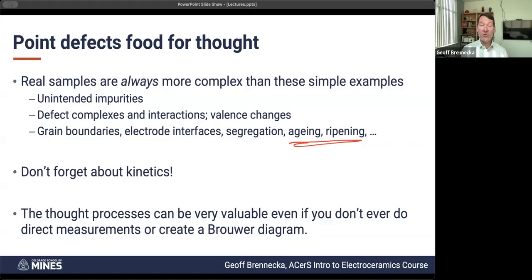But keep in mind, if you're doing these kinds of measurements, maybe your microstructure is actually ripening, maybe your grains are growing. If that's the case, you're probably at a high enough temperature that you're complicating things unnecessarily. So ideally, you're doing these measurements at a low enough temperature that the microstructure isn't changing. But maybe the kinetics are so convoluted and so slow that you have to increase the temperature to get that, but then you have to recognize that you've got additional stuff happening beyond just the assumed equilibrium.